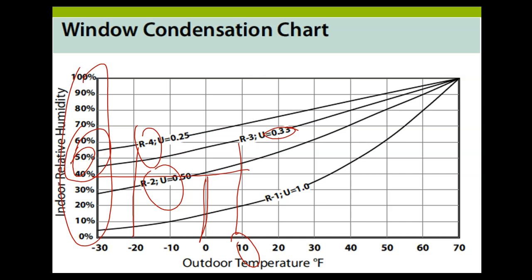If the humidity is above 60, you know something is uncomfortable about that place. You don't want the humidity to be above 60 at all. That's something wrong with the place. If you have a swimming pool or a hot tub, probably it's going to be a big cause of humidity in the house, and you need to get a dehumidifier.